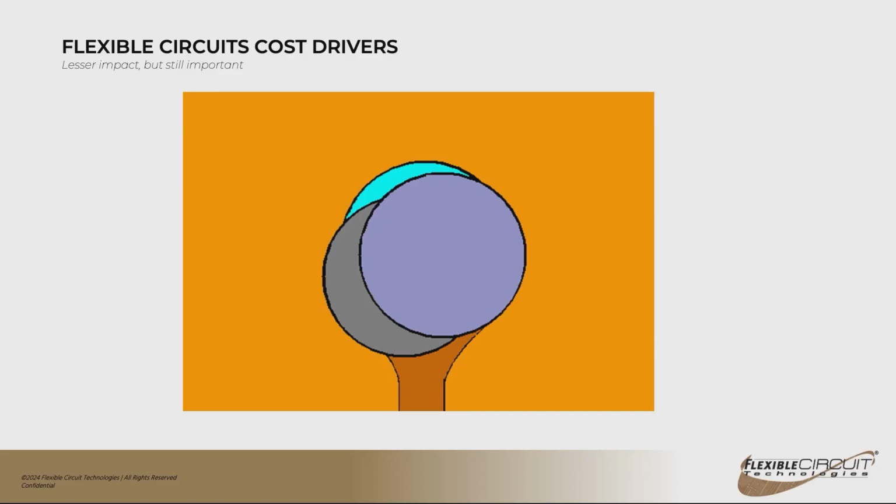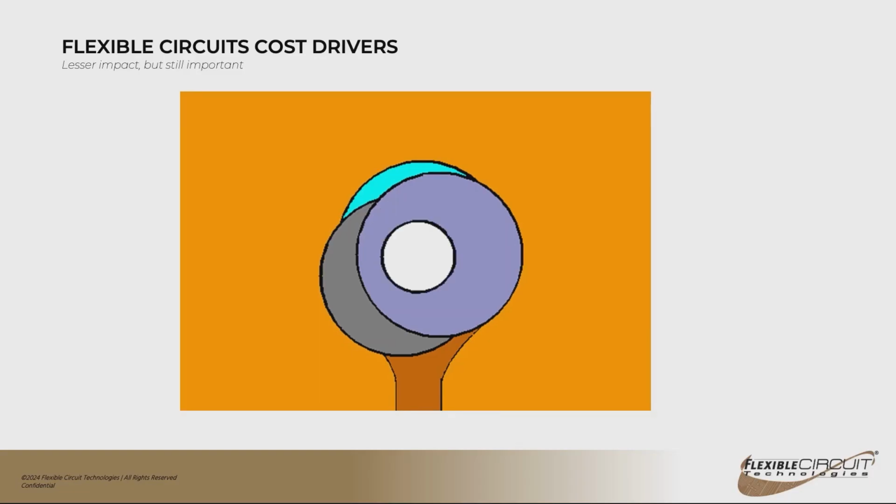Fortunately, most modern manufacturers have optical drills that will allow you to optimize where that hole is drilled and will position it in a place where you will have annular ring on all the different layers. However, as things get smaller, sometimes even the optical drills aren't able to put a hole in a place where there's going to be a pad.